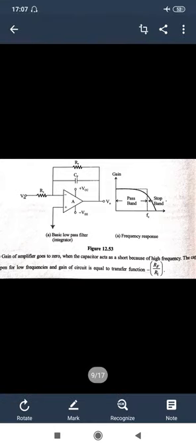It is basically the integrator circuit by which we have designed the low pass filter circuit. In this case, a capacitor is attached between the input and output as a feedback network, in parallel with the feedback resistance RF. So it works as an integrator circuit, passing the low frequencies and attenuating the high frequencies. When we talk about high frequencies, the capacitor acts like a short circuit. When the capacitor is short, the output gain of the amplifier goes to 0. So our output is 0 in case of high frequencies, and it attenuates the high frequencies.